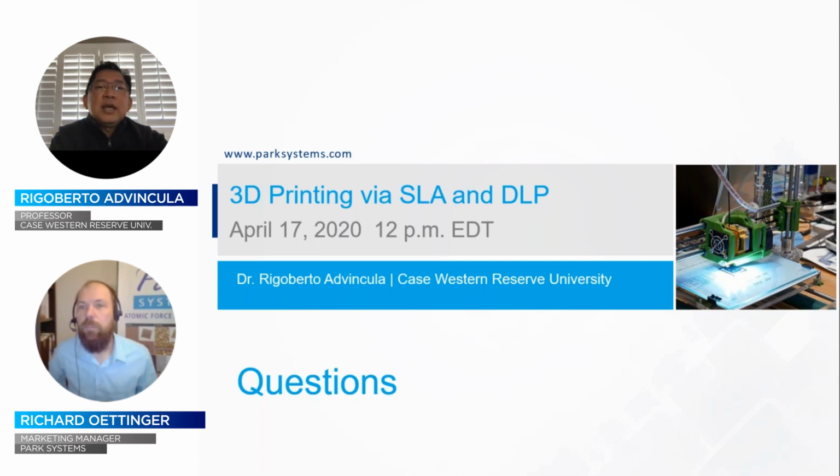But I would just say that the concentration is something where we look at the ratio between initiator, monomer, diluent, monomer, etc. There are published literatures that outline an ideal composition ratio between those species in a resin. Of course, one can say that the more initiators you have, the faster the reaction, or the more cross-linkers you have, the more thermosetting the properties are obtained, etc. So those types of optimization on the resin components concentration can play an important role.